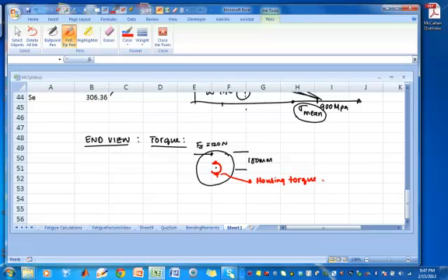That's the torque that you get from your hand, right? When you hold it and you try to do the disc sander, it will try to twist, you know, so you have to prevent it from twisting. That's the torque there, and it has to balance out this one, so it will tell us that T must be equal to 120 times 100, which is 12,000 Newton millimeter.